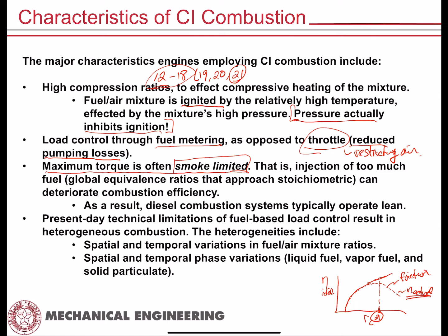So you have to do those 4 physical processes: penetration, breakup, atomization, and vaporization in order to get the fuel to the point where it can chemically ignite, okay? Those are all physical processes. One thing to always remember, physical processes always take longer than chemical processes, okay? So those physical processes can literally take milliseconds, whereas the chemical processes can take microseconds, right? They're at a much smaller, shorter time scale, okay?